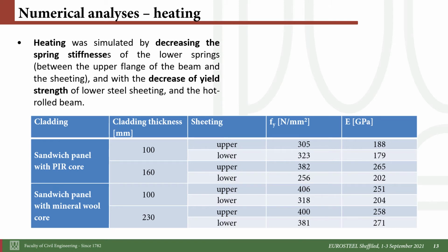The temperature load was applied by its effect, so we changed the material properties of the steel and the panel as well, so we decreased the yield strength, and we increased the spring stiffness of the screws as well. With the other presentation about this as well.